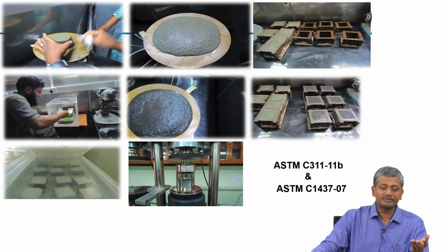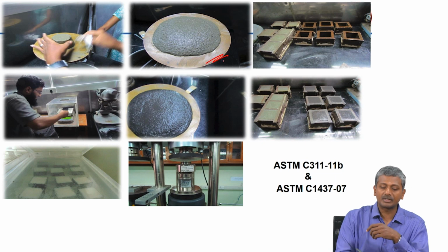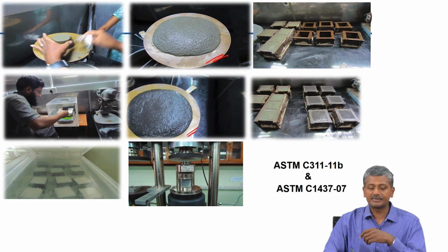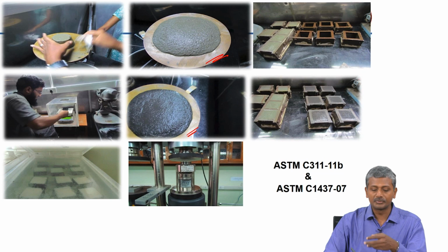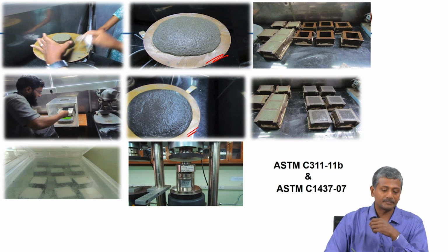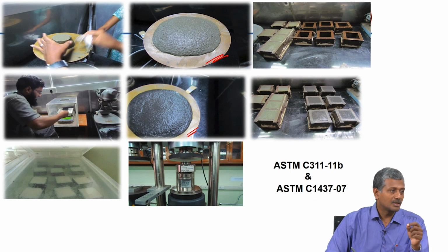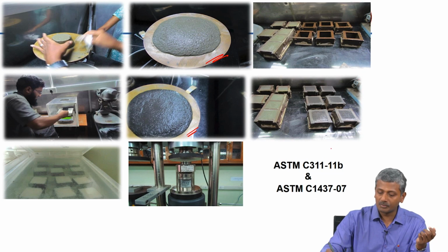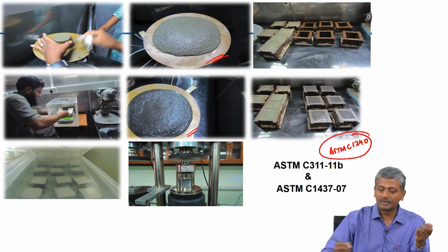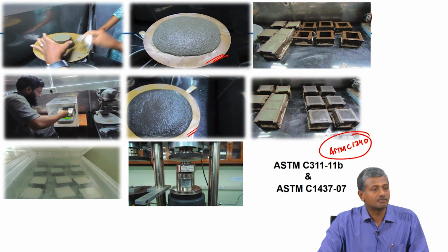In the strength activity test, the flow determination is done with the control system and with the blended system, and finally you produce 5 centimeter cubes and test them for compression. In silica fume based determination, you replace cement with silica fume, then add a superplasticizer to the silica fume based system to ensure the same flow as your cement based system. Silica fume is covered by ASTM C1240, which covers the determination of activity of silica fume.